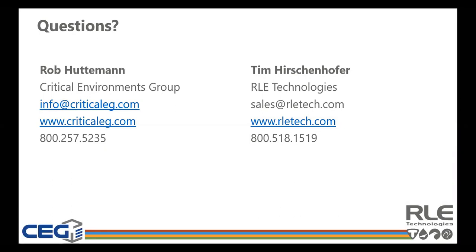And Tim, I know you'll have an answer for this one. Are directional floor panels really effective? Yeah, they really are. I've seen head-to-head competition between directional floor panels and a standard high flow airflow panel. You have to take some things into account, like the direction of the airflow under the floor.